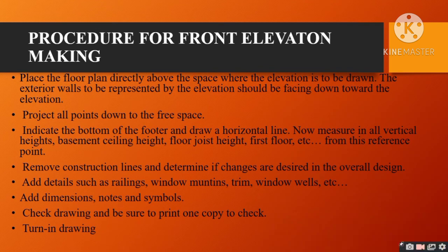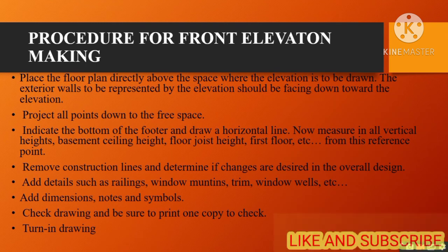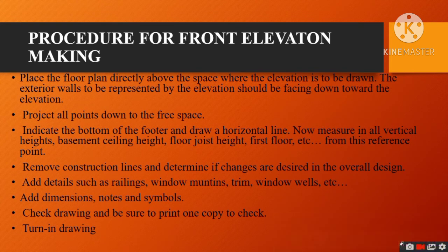Add details such as railing, windows, mounting trim, window wells, etc. Add dimensions, notes, and symbols. Check the drawing and be sure to print one copy to turn in. So this is the actual procedure for making a front elevation with AutoCAD. Not only AutoCAD, you can draw in engineering drawing also; the same procedure you can follow.